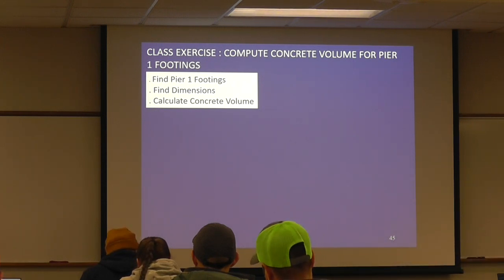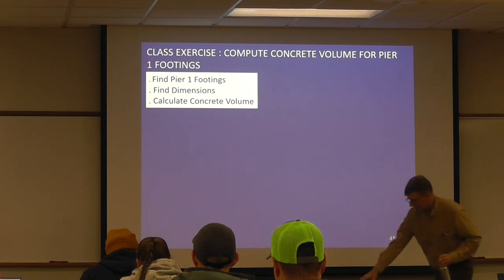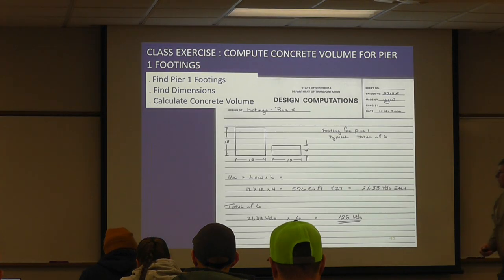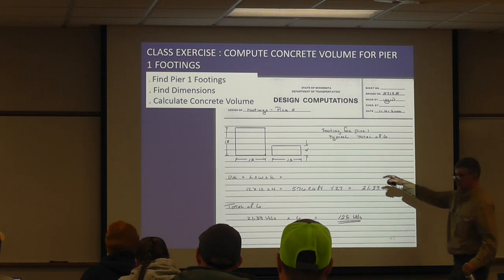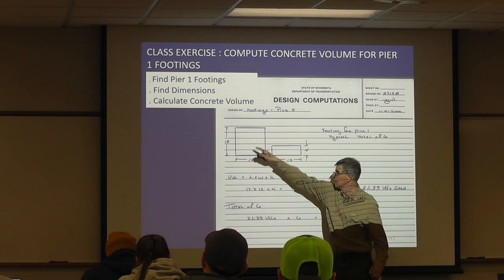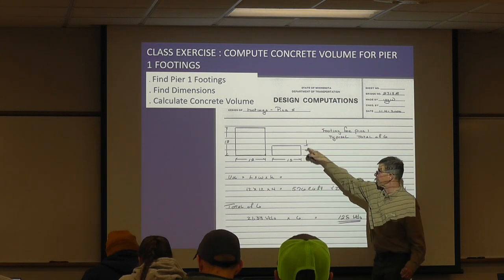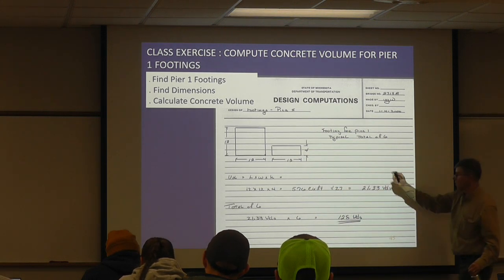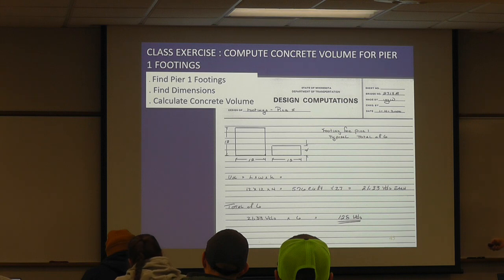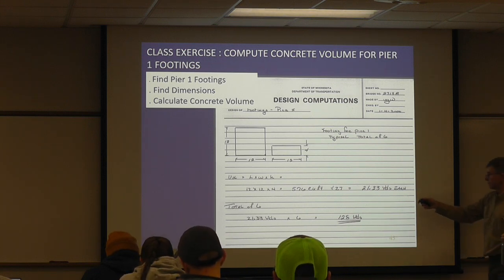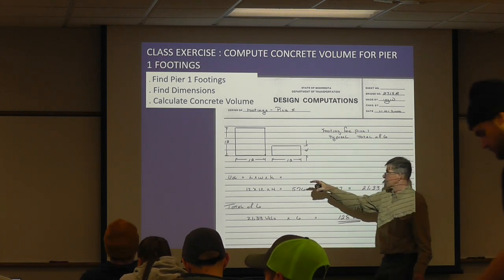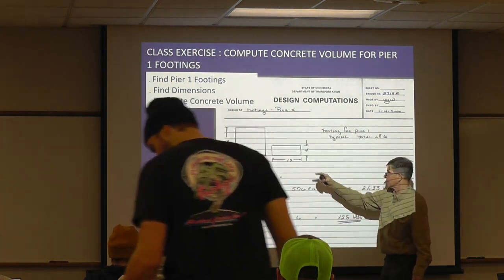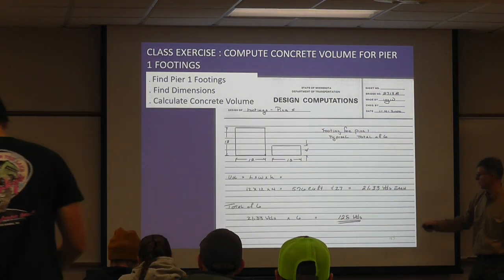Okay, let's see what we have. So you found that it's 12 by 12 in area, and the thickness, so plan elevation 4 feet. So 12 by 12 by 4, simple math. Again, there's multiple ways we can do it. We can take cubic feet and then divide it. I mean, literally, you could put this into yards, divide each one by 3, and then do it.